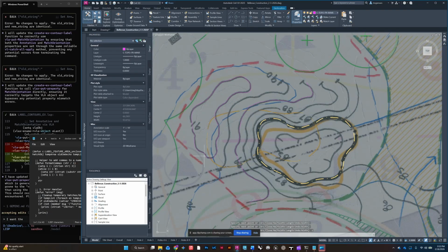Close. And now this, because we didn't snap it to anything, has an elevation of 0, so you need to make sure that you fix this by putting in the correct elevation. So double click, 91, enter, and now this has an elevation of 91. Again, that's important because then it makes it so we can go in, we can check it, we can make sure that everything's right, and if we were to take this into 3D, this actually has an elevation for creating a terrain.